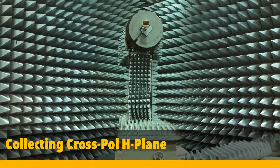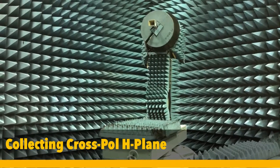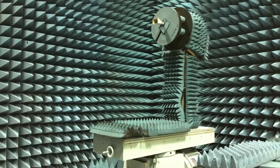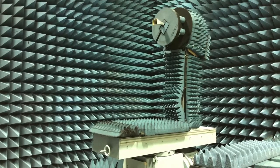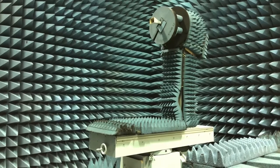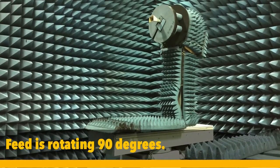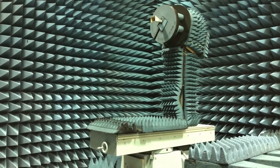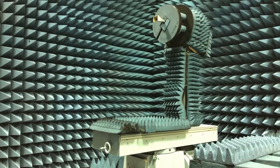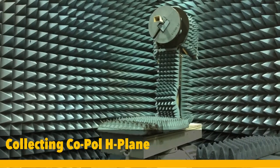So as you see, the absorbers in the back of the horn, we could have done a better job, but this is just for demonstration in this case. So this is right now at +90, so it's going to stop. Now this was cross pole H-plane. The next step would be copole H-plane. Now this noise in the background is the rotation of the feed to make the polarization match again. Since we have not touched the antenna under test, we are still in H-plane, but now the polarization is matched, it's copole, so it's becoming copole H-plane.